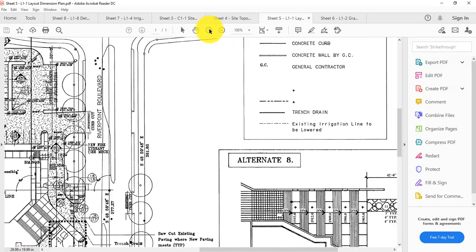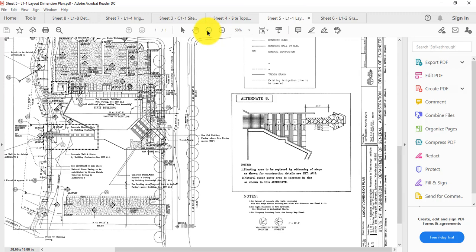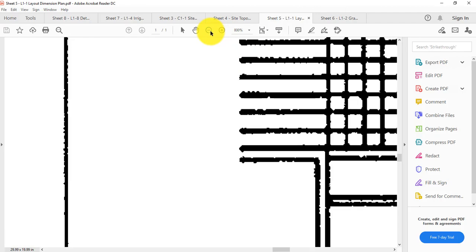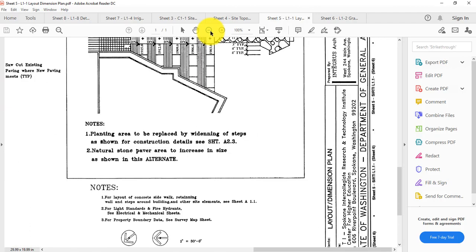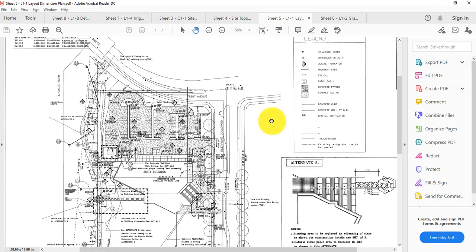the grading, and where are we at? It's a layout of the building and a few details. You'll see that the building's true north is to the left. You'll see where the catch basins are. There's small little boxes right there in the corners of the parking lot. And if you look at the contour lines, they slope to those catch basins.